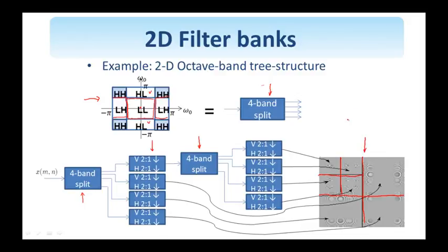So this is actually an example of a multi-rate subband decomposition, because the bands are not all of the same size or of the same rate. And in practice, that's how we obtain subbands, either equal rate or multi-rate, just using one pair, either 2 filters for a one-dimensional signal or 4 filters as shown here for a 2-dimensional signal.